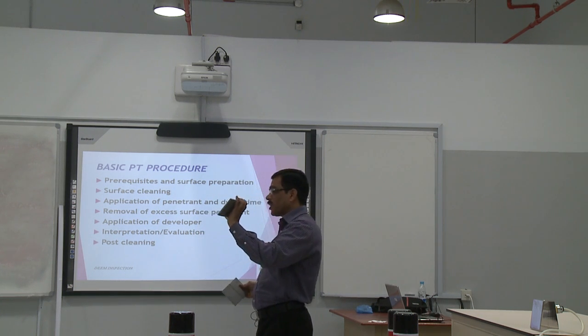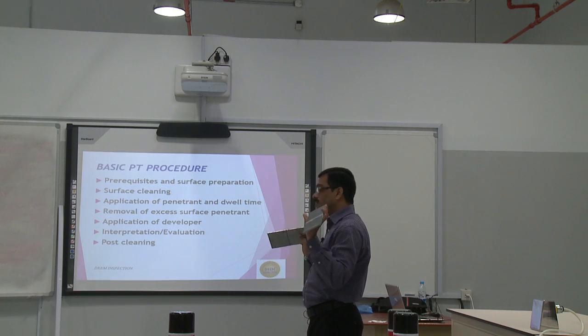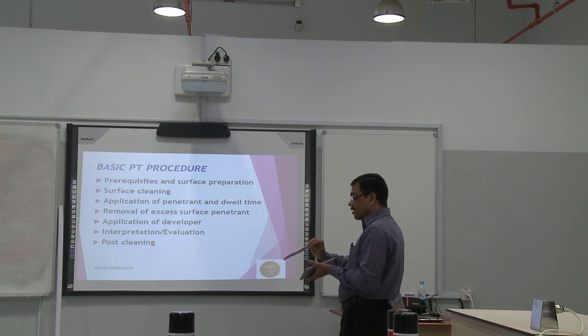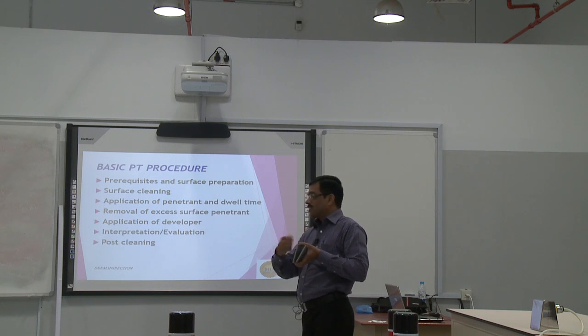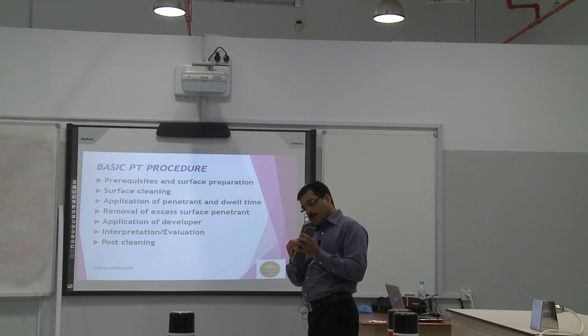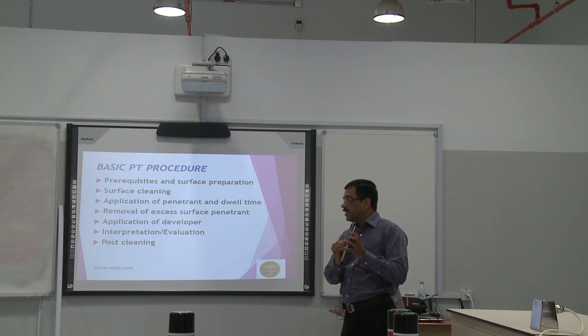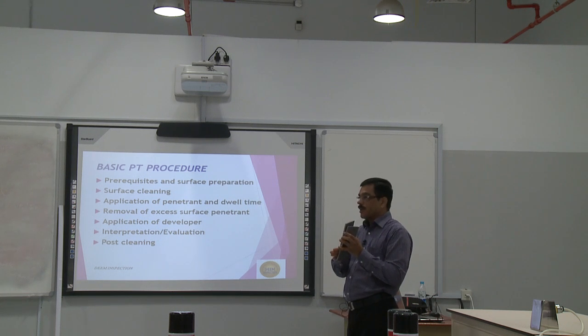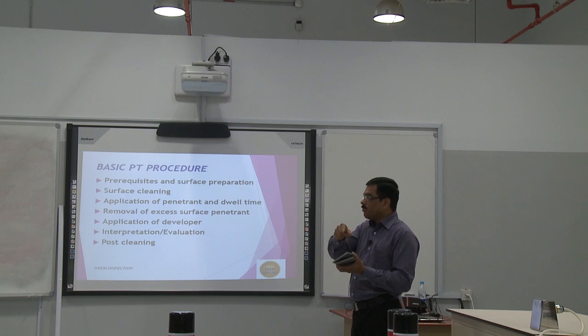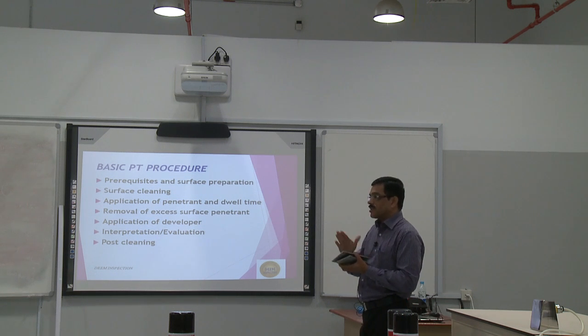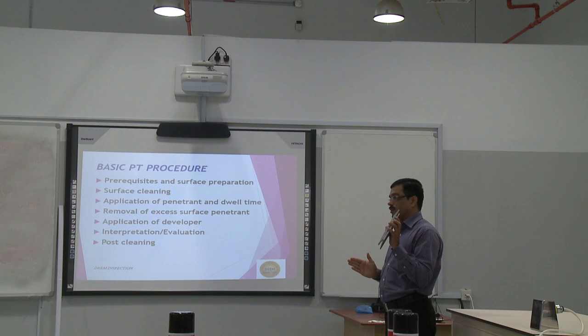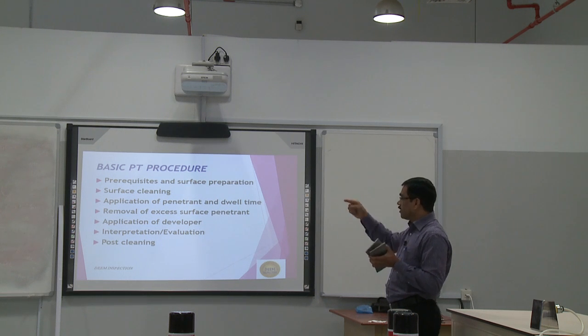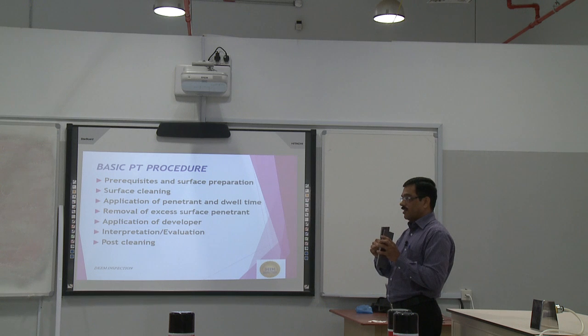Whatever condition the product is in when it comes for testing, that is the prerequisite. In this case, we are saying do not do sandblasting, because if there is a minor crack, like yesterday we saw one, sandblasting may close it. Sand may enter or smear the openings, so after applying penetrant there is a chance of blocking it, or we cannot detect the discontinuity. After the prerequisite, we have to do surface cleaning again to remove any oily contamination.